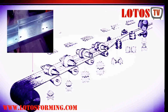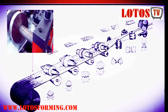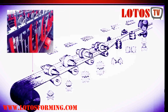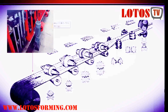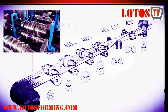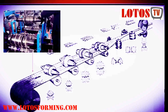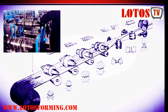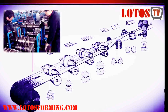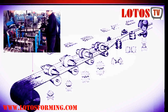So the dimpling process is a process that is applied prior to the traditional cold form process. In this dimpling process, we use a pair of 2 rolls with a special desired pitch on the outside of the rolls so that we can stretch the flat strip to apply the dimple above or below the strip to develop it into the dimple strip.